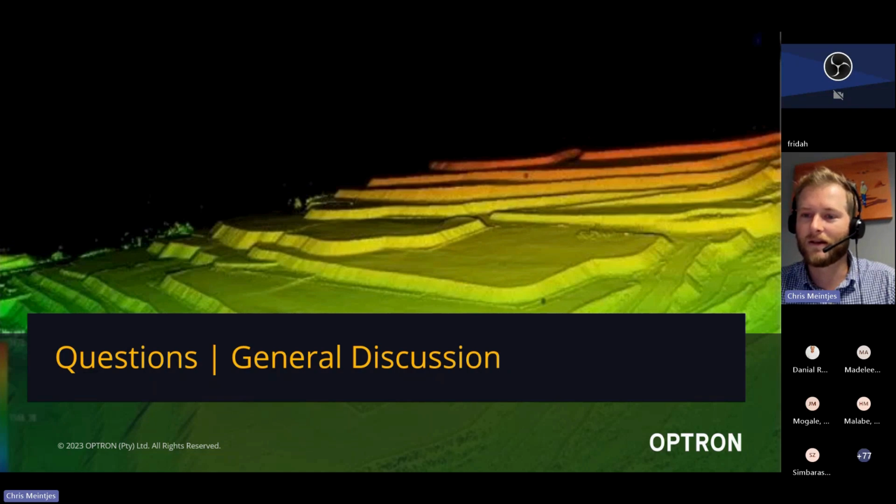Okay, so Erasto, in this presentation, I see you specifically identified and explained scan data. So how about data captured manually by either GNSS or Total Station? Well, TBC is a great software for GNSS and Total Station data. It's not going to do the point cloud classification, obviously, but you can use your GNSS data or your Total Station data exactly how you would in a package such as Model Maker.